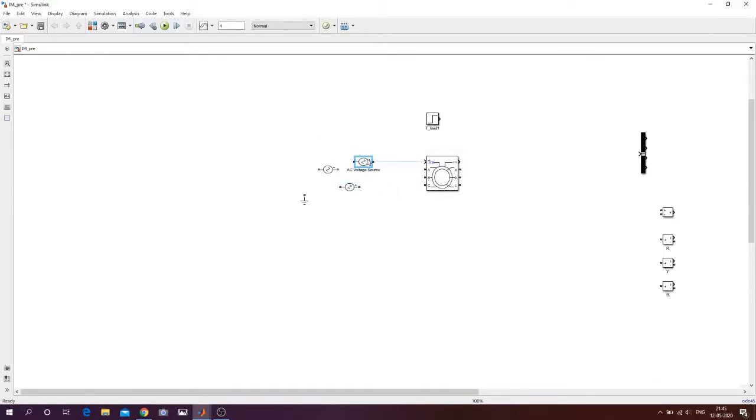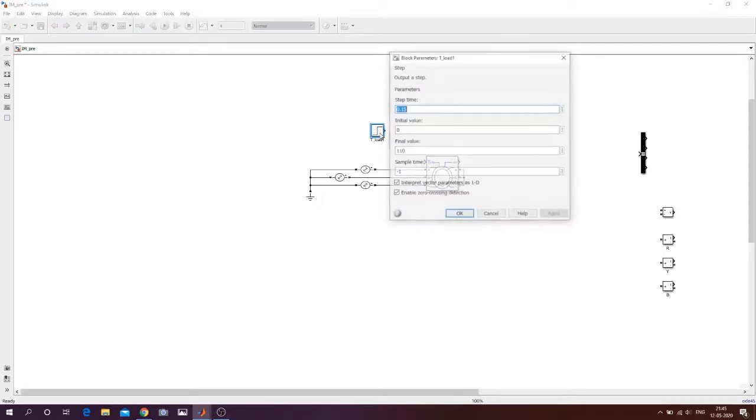Then I would connect it with the motor over here. So going over here, this will be going over here, and the star connected supply. The other parts are connected to neutral and it is grounded. The rotor part, that is this ABC, should be short circuited. Now a small amount of torque should be provided over here. So I am putting a small initial value.